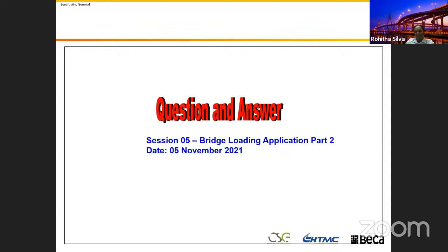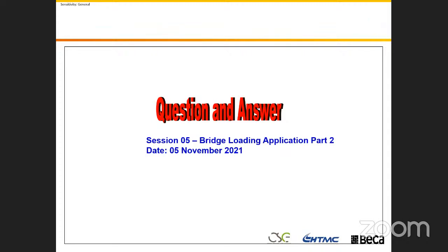Did I answer? Yes, Mr. Rohit, thank you very much. So I have used this 100 kilonewton and the HB vehicle load in the grillage analysis, and I got the HB vehicle load as the most critical one for the deck analysis and the overhang design. So I had some doubt about this 100 kilonewton. That's why I asked that question.